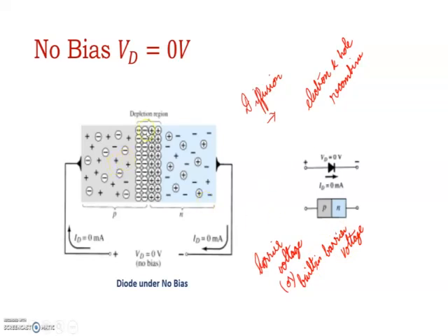Because holes, which we know are positively charged, will be attracted towards a negative, but here we have positive, so holes will not move through the junction. Similarly, the electrons cannot further move through the junction. So this depletion region acts as a barrier for further diffusion.